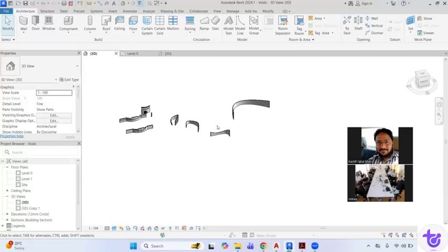It depends on the geometry which we are creating. Maybe, for example, if we have an arc, and that arc is start, end, and center arc, 3-point base, so better to make it a 3-point. But if there is a shape which is having different curvatures, maybe a complex geometry, then as per our requirement, we have to increase more points, because more points you have in an adaptive family.